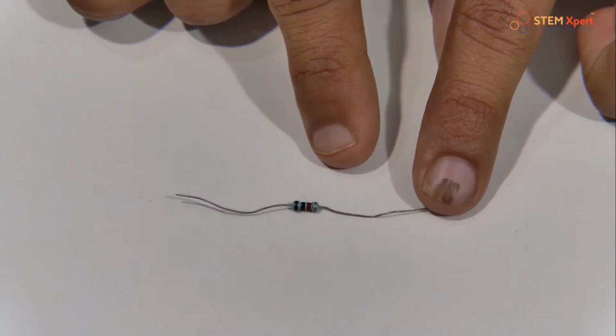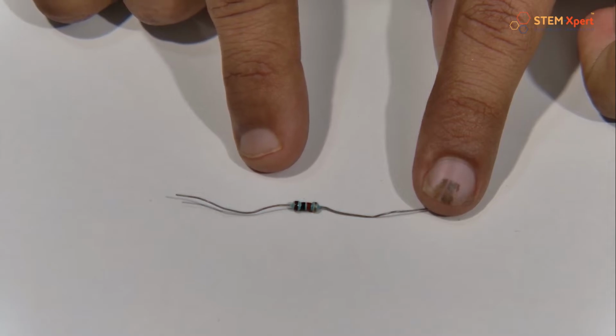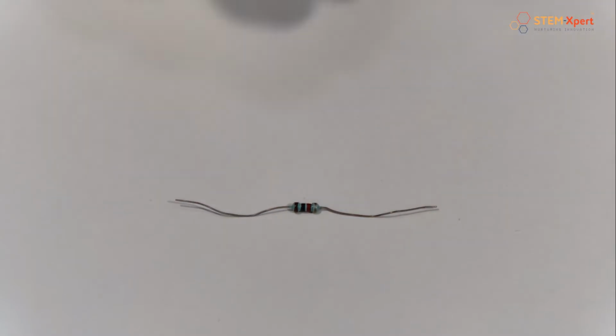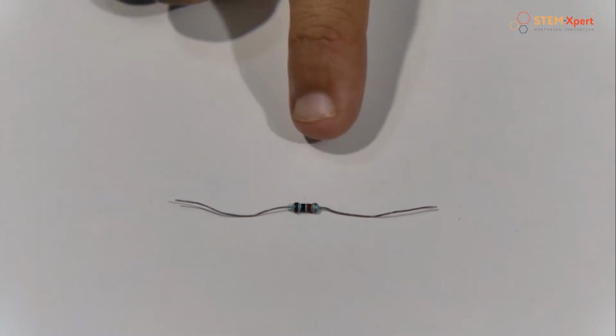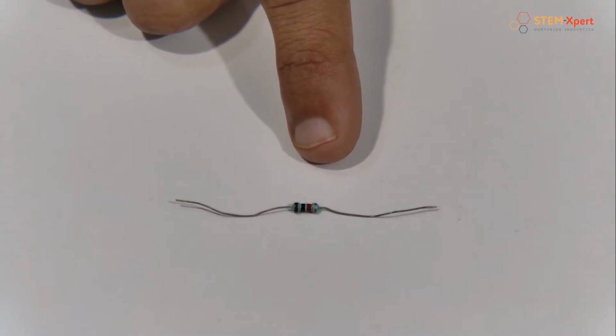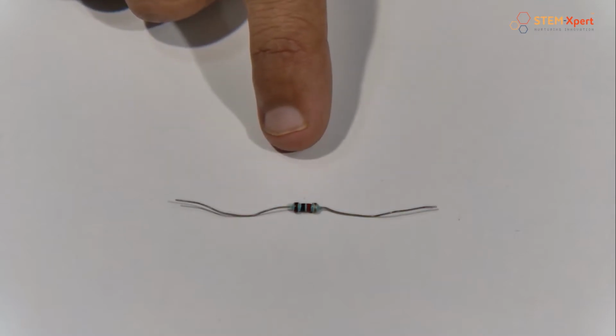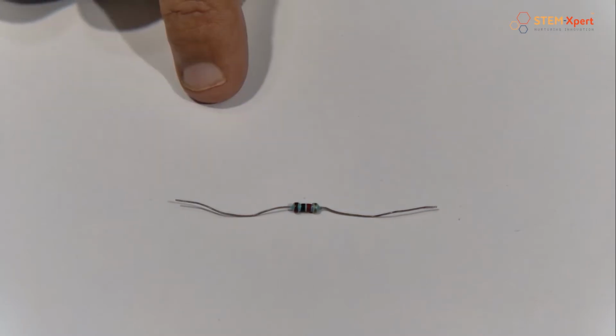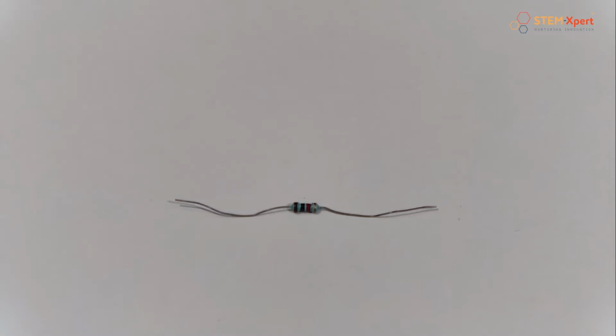As you can see, there are different color strips on our resistor, right? Yes. These are called bands. Basically these bands determine the value of that particular resistor. Don't you remember, here we are using 1 kilo ohm of resistance. So the configuration of our resistor goes brown, black, red, gold. That means this resistor is 1 kilo ohm of resistance. Also, resistance is measured in ohms. I hope you have understood the concept of the resistor.